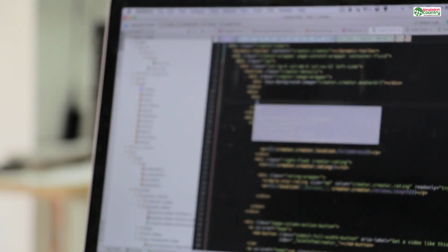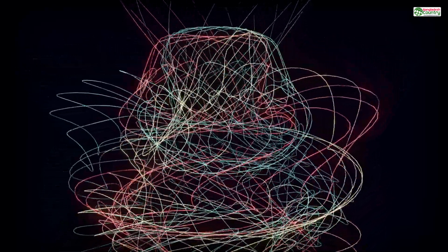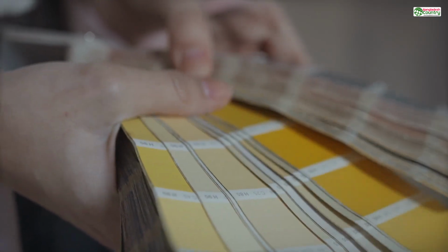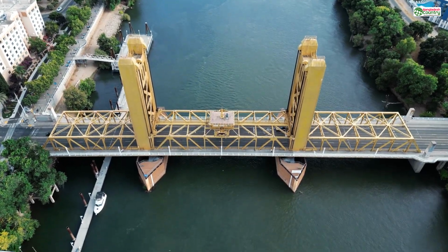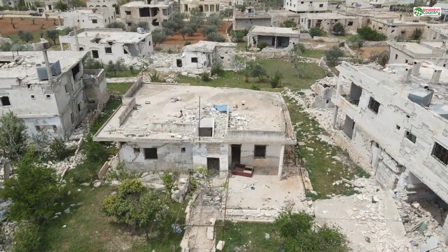For more complex, jagged holes, you may need to do more delicate work, selecting two edges on opposite sides of the hole, and using a bridge tool to create a new face between them, slowly rebuilding the surface one piece at a time. What about those inside-out faces, the flipped normals?